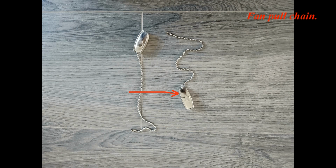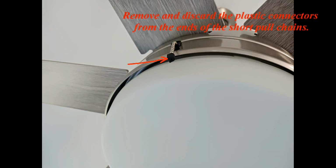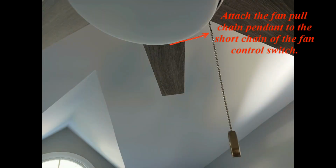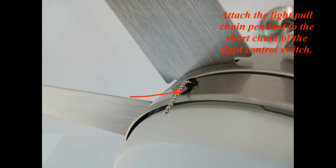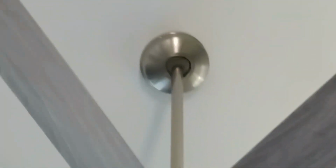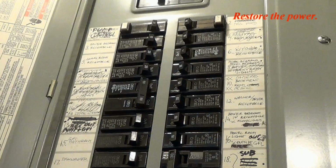Fan pull chain. Light pull chain. Remove and discard the plastic connectors from the ends of the short pull chains. Attach the fan pull chain pendant to the short chain of the fan control switch. Attach the light pull chain pendant to the short chain of the light control switch. Restore the power.